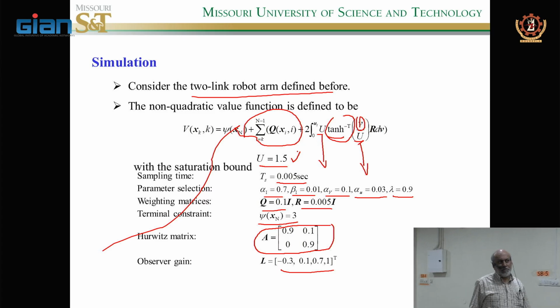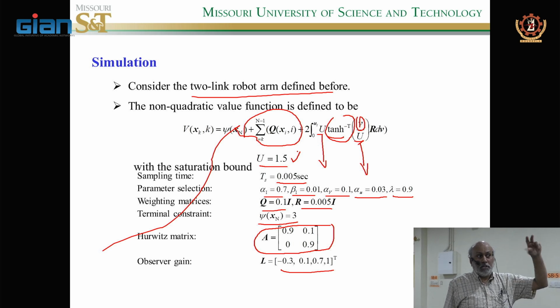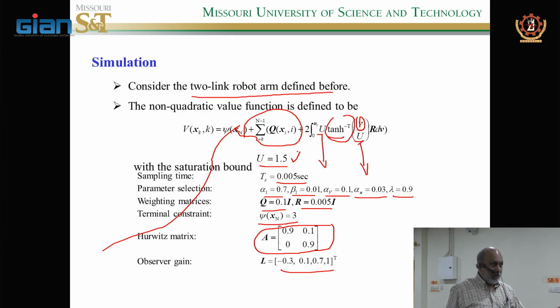And there are papers available, you can look at them. So it's no different. Her question was important, I was expecting that somebody would ask. There are 2 basic control problems. One is called regulation, the other is tracking. If you do tracking, the same controller would work for regulation. But if you only design a controller for regulation, it doesn't work for tracking.